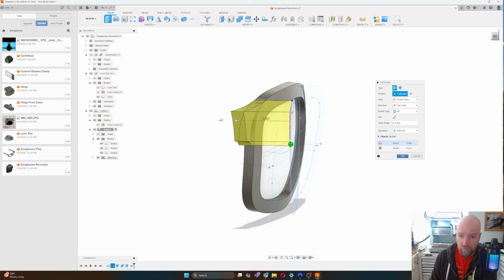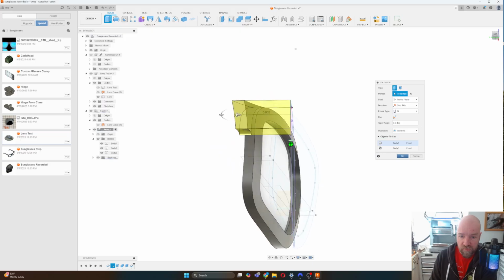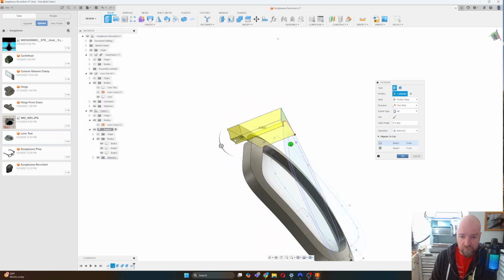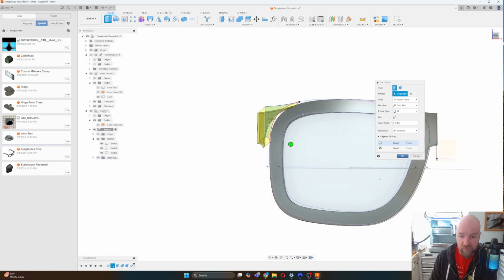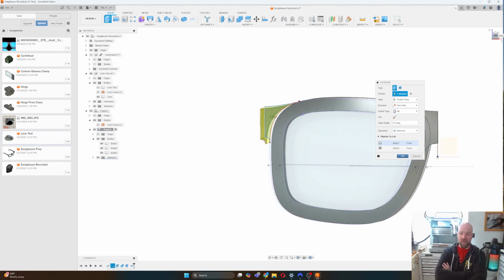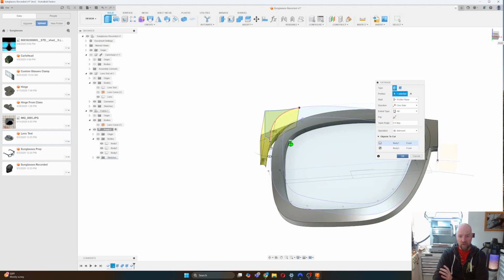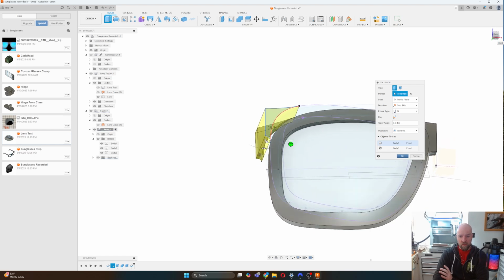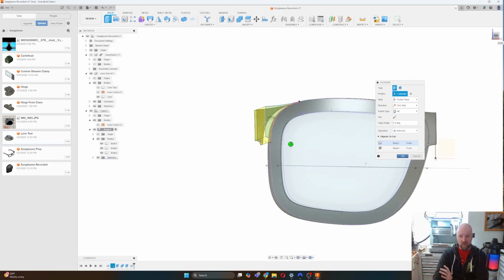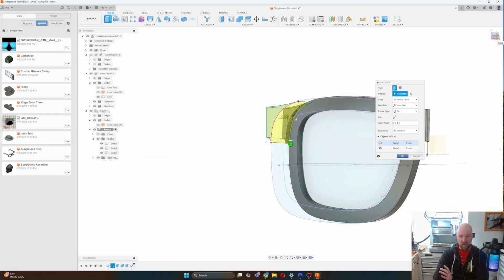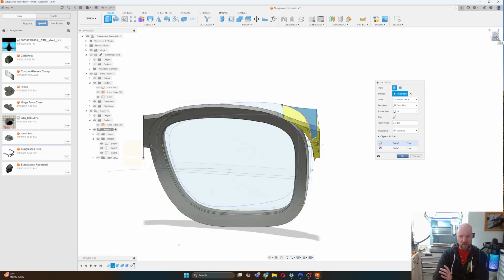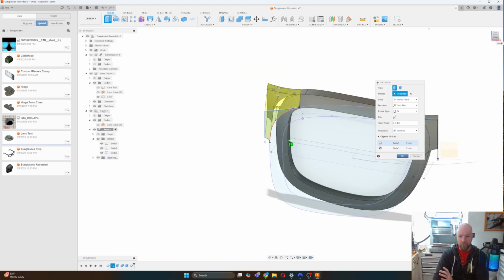It's not making it at the same spot. That's interesting. Oh, because my lens isn't made from the same profile plane. I need to extrude out more than what I've got here. Or, yeah, well, I need to move it over. Maybe I'll go that route. Although my curve's not going to match.